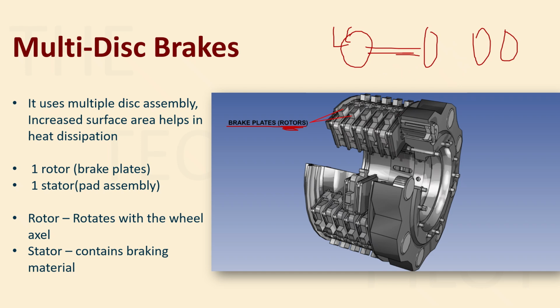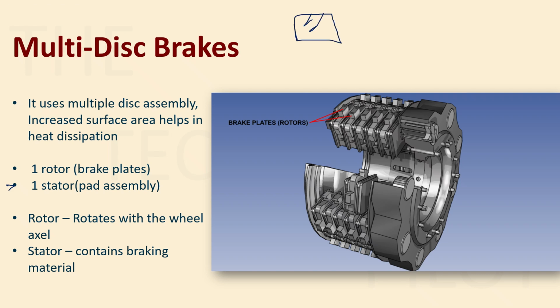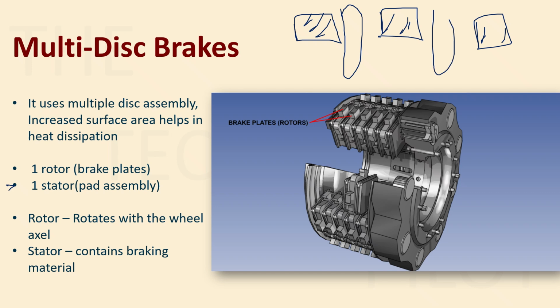And then you have your stators. What are stators? Stators are your exact brake pads. The brake pads that you saw, the friction pads, right? They're also known as brake pads and these are stationary. So they are attached on the mountings, right? So these pads are stationary and you have your rotors in between them, right?